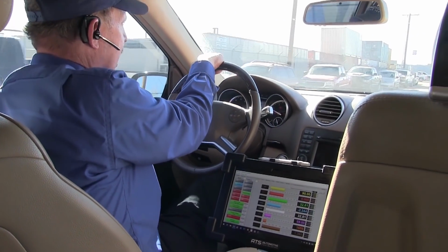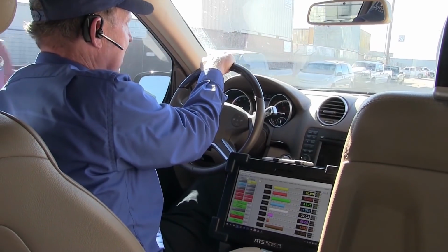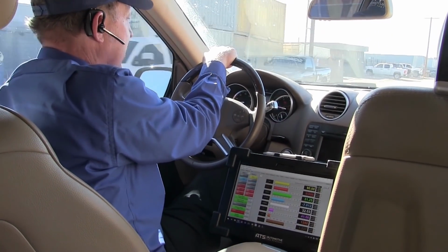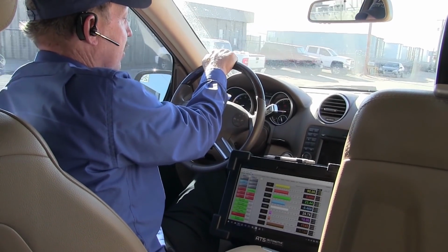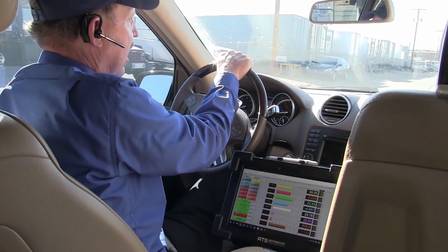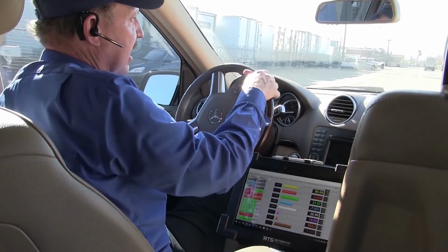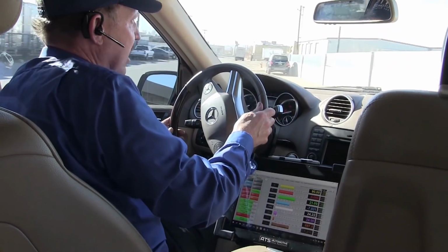So I always like, when I'm on a test drive, to know what I'm coming back to the shop to test. If you don't know what you're testing on your test drive, you need to keep driving the car until you know what you're going to test. Otherwise, you're just wasting your time.